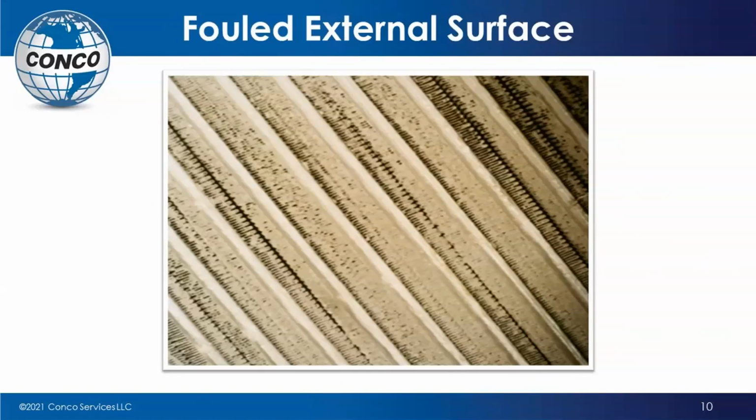But if you take a look toward the center of that picture, especially the center bottom portion, you can see that those fins are completely blocked. And so what's happened here is you've restricted airflow completely. So now what we have is a situation where the air itself is less dense and doesn't have the ability of water to do that heat transfer. And now you're adding an energy penalty in the summer, plus the fact that we have limited how much air can get up through those fins. We've eliminated our surface area. And that is the real key. That's the key to the ACC unit, is surface area.